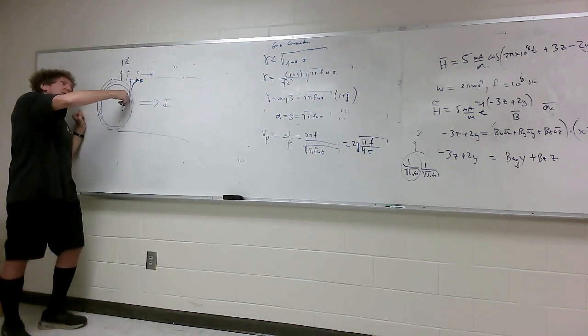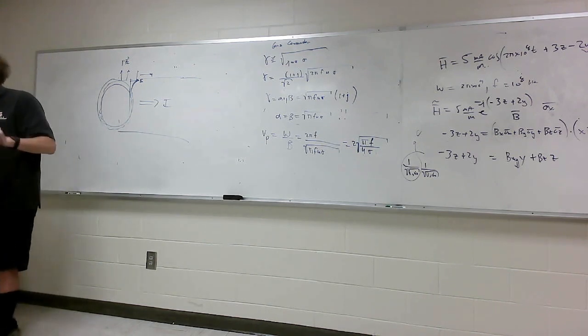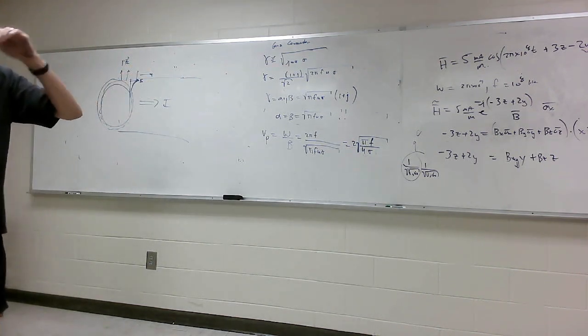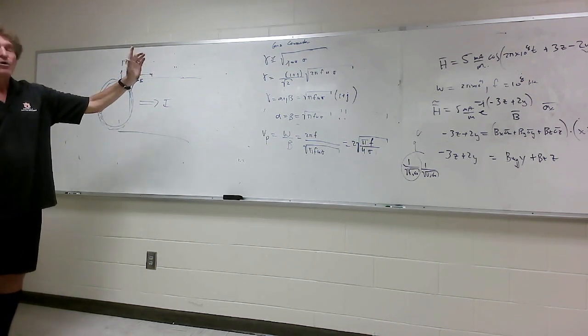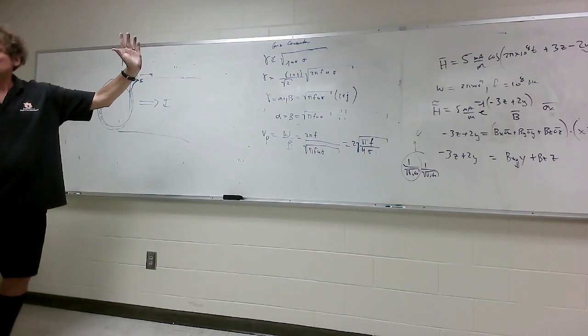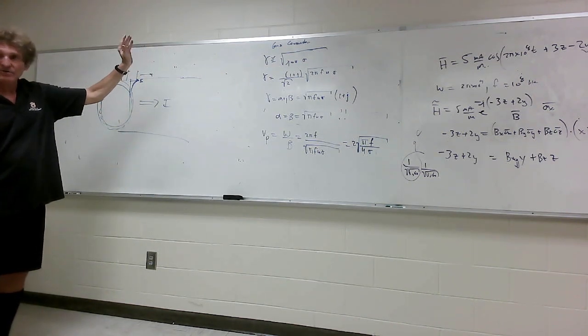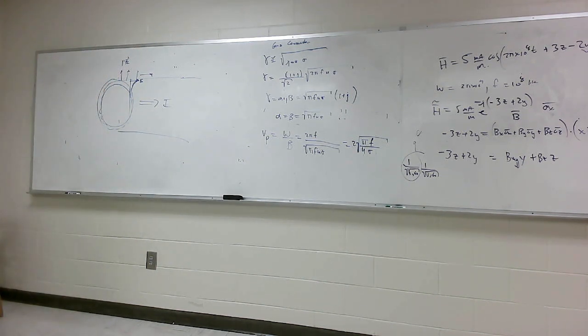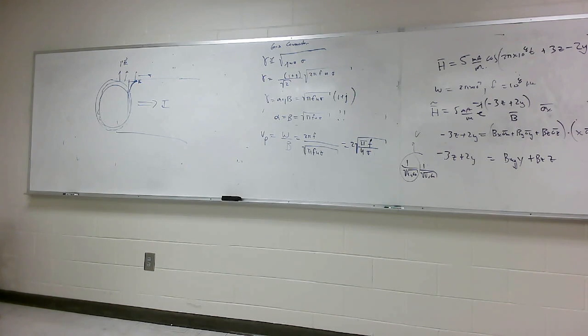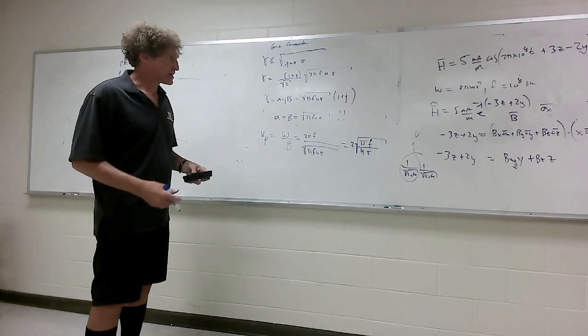But the speed that this thing is propagating towards the center of the wire is the phase velocity that indicates. Has nothing to do with this, and that's a common mistake unless it's explained. The thing will always propagate at basically the speed of light, unless there is a dielectric media in between. When you have electric fields propagating on wires, usually you have what? You have current going down one side, coming back the other, or you have some circulating current. You have to have something like that. And that will cause this wave outside of the wire to propagate at approximately the speed of light. This is important.